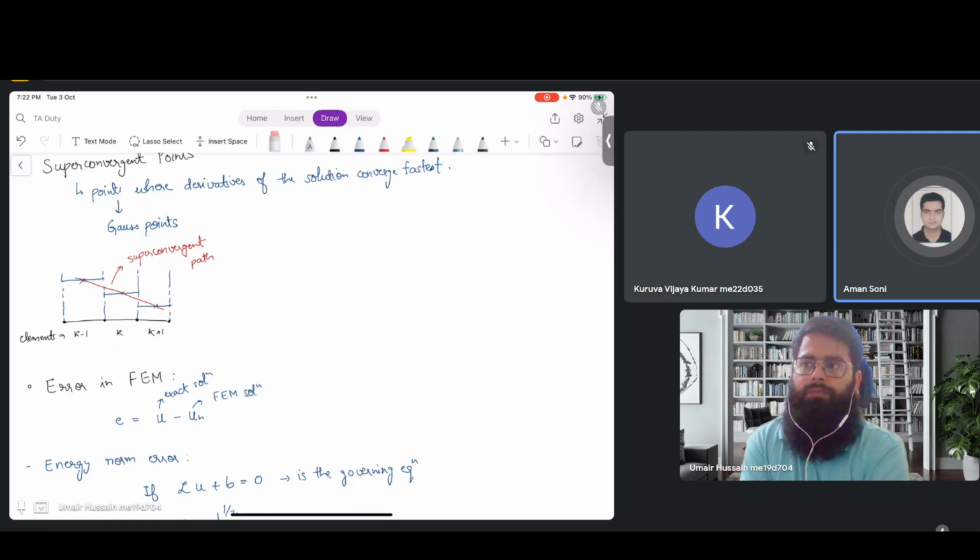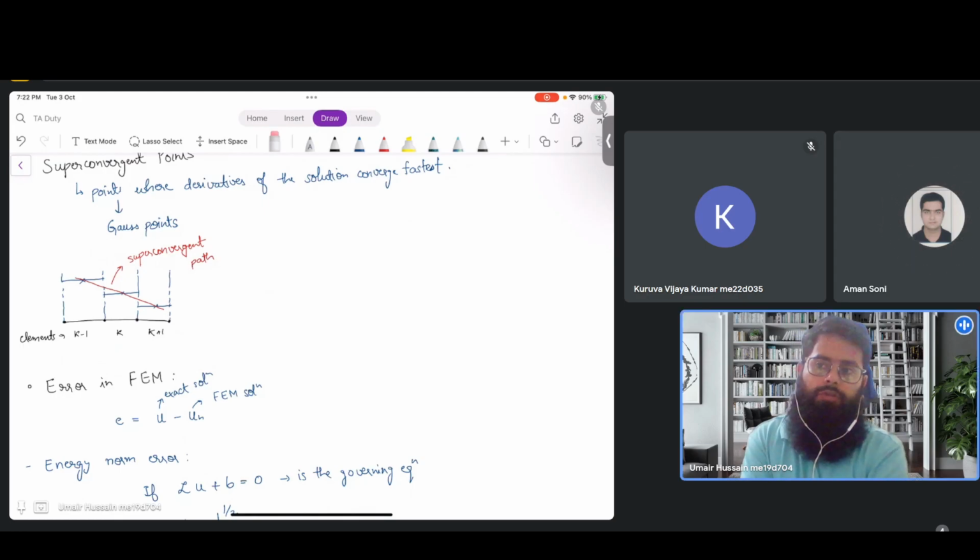What is the actual meaning of convergence in FEM? What you're saying is right. In very rare cases, if we know the exact solution, we see that as we take any action that reduces the error, which we call refining the mesh, the solution approaches the exact solution. So we see that it is converging.